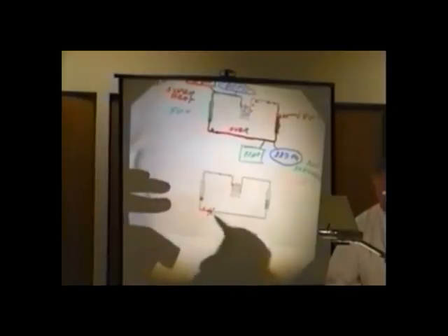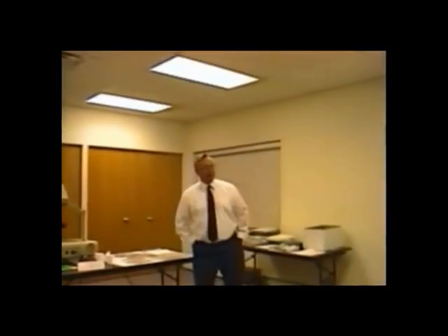Now let's restrict it. Let's say the contractor wanted to save $7 on a $3,000 job and he doesn't put a dryer in here. Let's just say that. And so he's got a piece of something that gets plugged in the orifice. Now let's stop here. If you can diagnose a complete 100% restriction, you'll be able to diagnose a partial restriction because it's just not as bad. So 100% restriction, no flow.